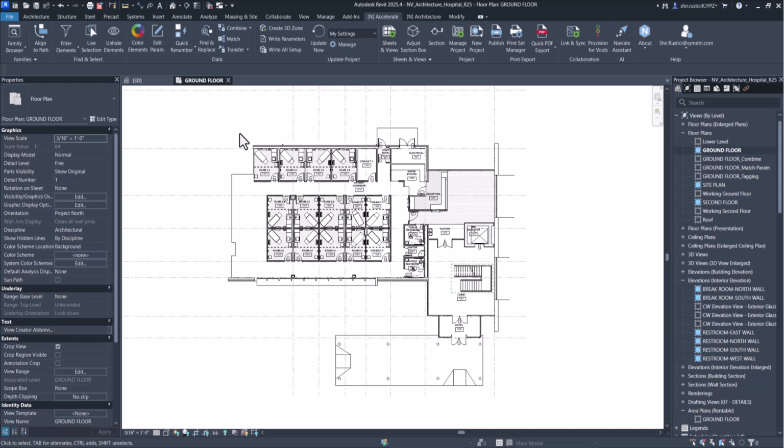With this improvement, upon running the Unhide Elements command, you are now presented with a categorized list of the hidden elements. This allows you to selectively unhide categories. You can choose categories you wish to remain hidden, and then these settings will be saved per user. So I've gone ahead and hidden a bunch of things in my view.